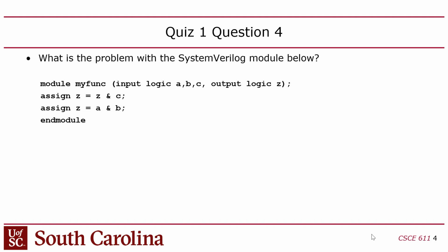It's a cross-coupled connection. Having a statement like that could cause ModelSim to freeze up, because you end up with this combinatorial loop, right? The simulator keeps trying to update Z, but every time it updates Z, it has to update it again, because Z appears on the right and the left-hand side of that assignment. The left-hand side is updating Z, and the right-hand side is acting as a trigger. It's causing that statement to trigger.